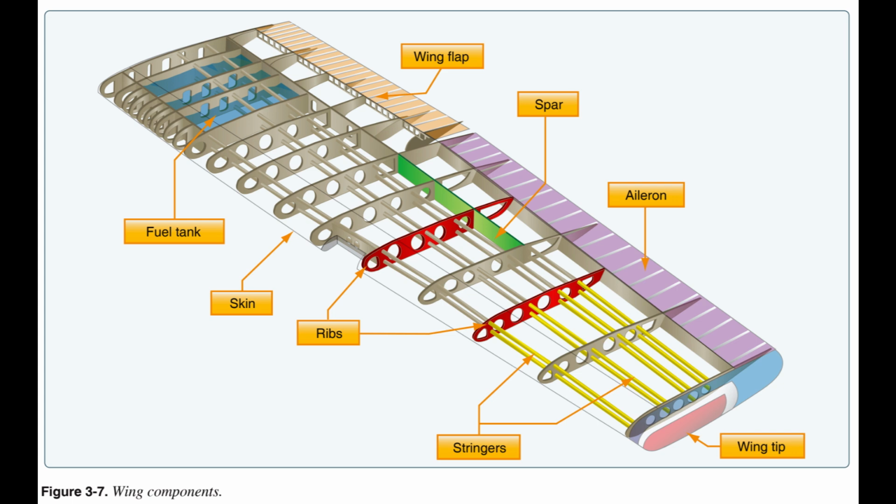These are reinforced by trusses, I-beams, tubing, or other devices, including the skin. The wing ribs determine the shape and thickness of the wing, airfoil. In most modern airplanes, the fuel tanks are either an integral part of the wing structure or consist of flexible containers mounted inside of the wing.